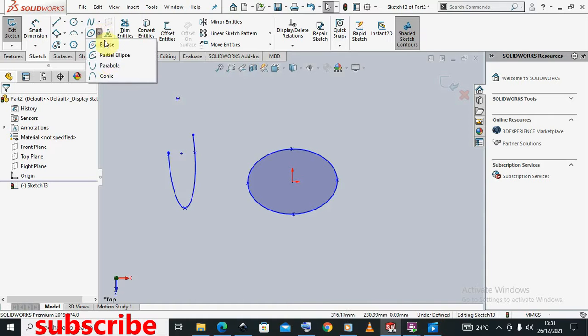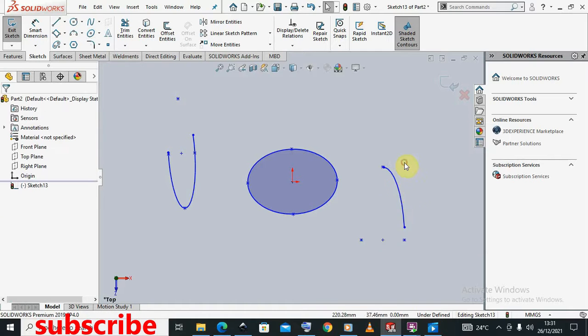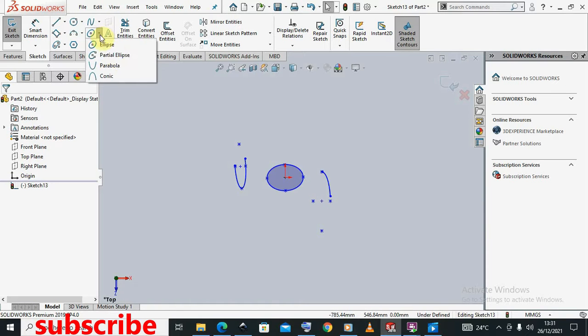So that's the partial ellipse. Maybe once more, you click, drag, then you move, click twice, then you move around. Since it's a half, it can even be just an arc like that, you see. So that's the other part of the ellipse. That was the partial ellipse.